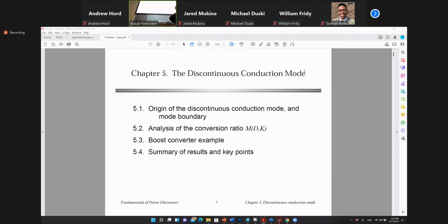Okay, and that's the simplest way of operating the converter. So by knowing the mode of operation, you can only switch this and treat this as a simple diode, as if there is no MOSFET. Is that clear? Because it has a body diode.